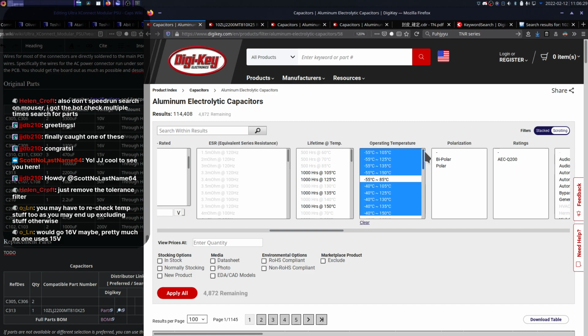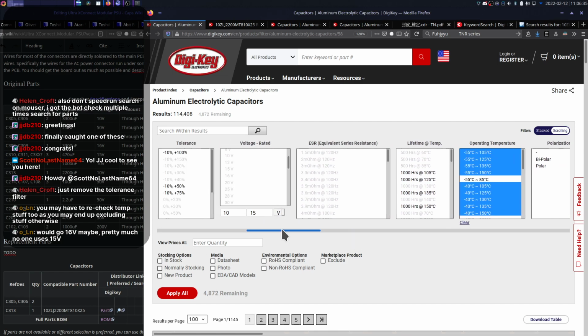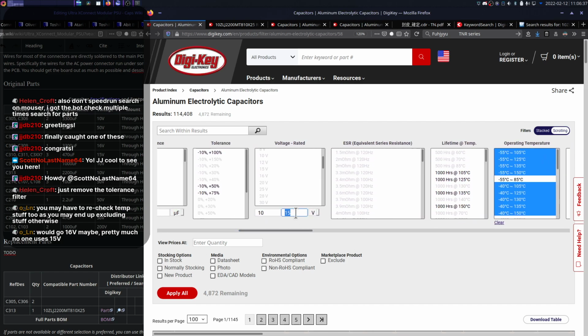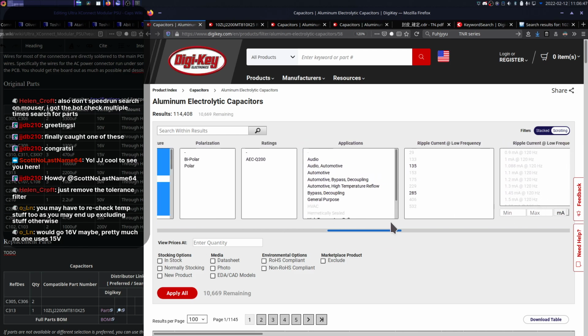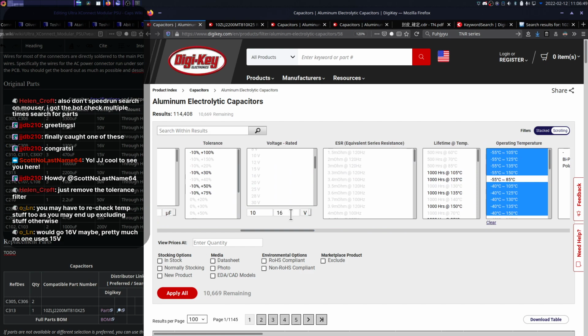Oh, no, I think I just cleared it. Nope, okay. We'll go 16 volt. Pretty much no one uses 15. Well, I guess, yeah. Thing is, I don't really want it to be that much higher. The higher you go, the worse the ESR characteristics are. So I don't really want it to be too much higher. So that's kind of why...